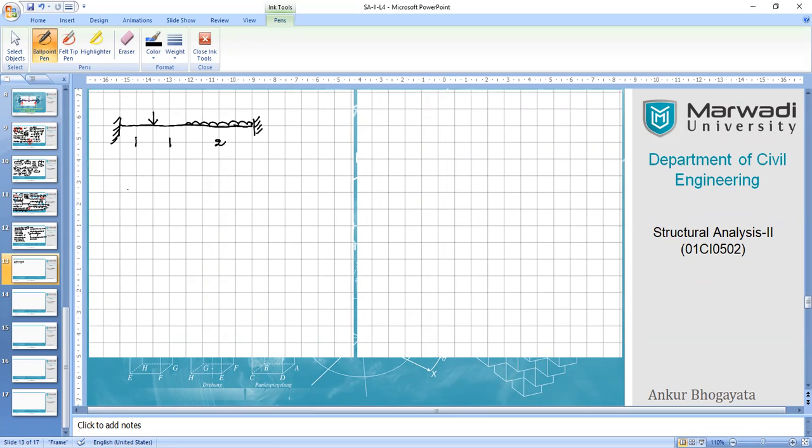All right, so we can now draw our diagram. You know that the span moments are yet to be calculated, right? You can draw the span moment, but however here we can simply draw, first of all, the end bending moments, right? And we know that MA is larger than MB, so we can draw it accordingly, and we can simply connect both the values directly, right?